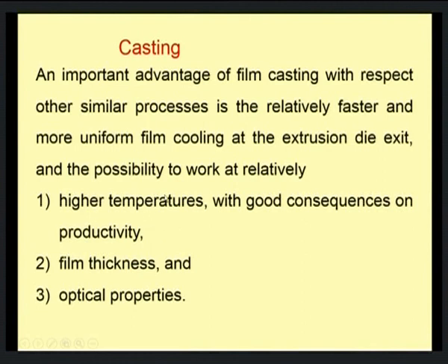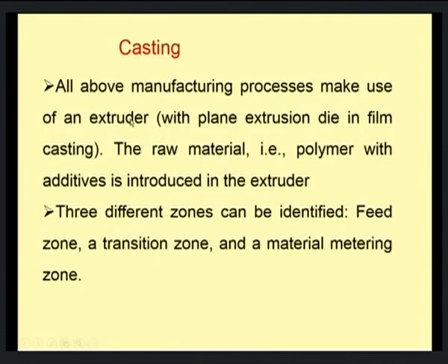One need not bother about the high temperature at which the extrudate is going to come out of the extrusion die. As a result, this will improve the production rate. And with respect to film thickness, if you are able to achieve continuous cooling, then there is no problem with film thickness, and at the same time the optical properties would also be better in extrusion film casting.